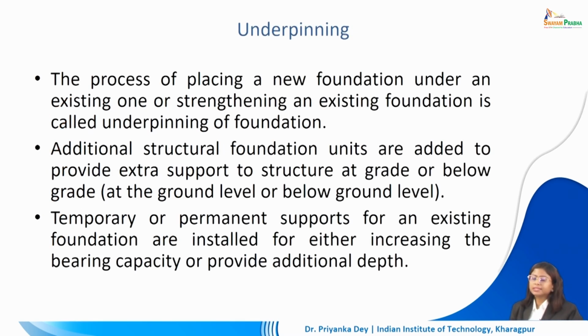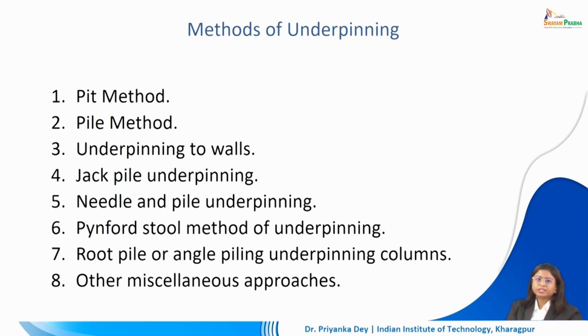Underpinning is a process by which we replace an existing foundation with a new one. So we do not want to damage the building above it. We just want to isolate that superstructure and create support for it so that we can work underneath and replace certain sections of the foundation one at a time. Now generally we replace alternate sections of the foundation. So this can be done again by various methods.